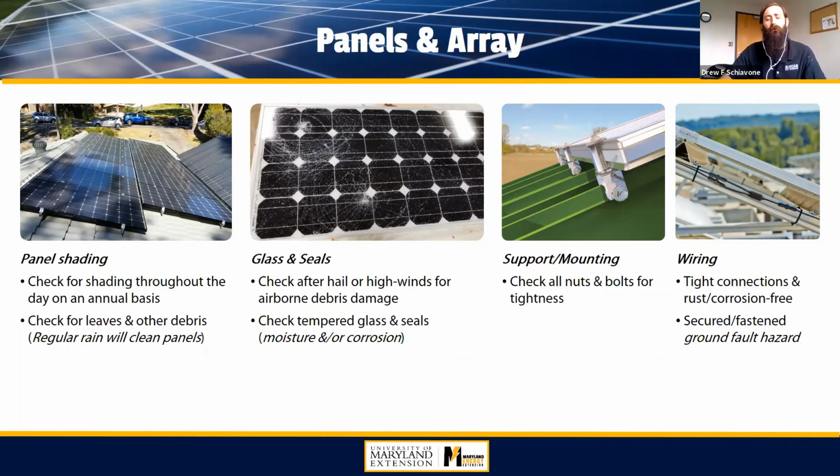So some people wonder if they'll have to scrub the panels, not necessarily. Of course, if your panel is broken in any way, if the glass is fractured like what happened with the rocks on this module, you want to make sure to replace that module. I've heard of people trying to repair them. I don't think that works really well. I haven't really seen that firsthand, but you probably want to replace the module. Even if it's a small fracture, make sure there's not water penetrating into the module and causing any corrosion.